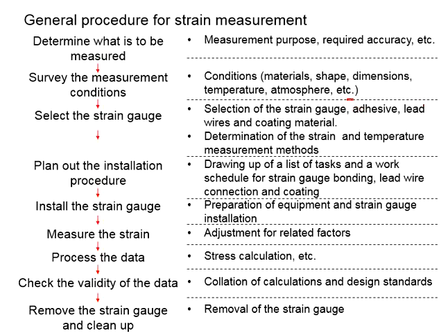You will need to choose the right adhesive to ensure the bond between the strain gauge and the testing material. Some are applicable for steel, some are applicable for plastic, and so on and so forth. You will have to consider the lead wire as well as the coating materials. The coating material provides protection to strain gauge from moisture, from abrasions, and so on and so forth.